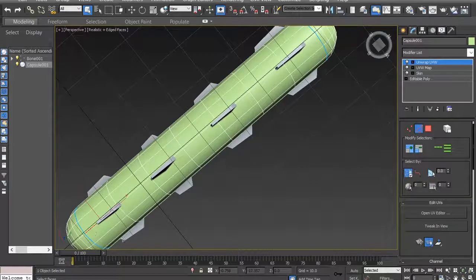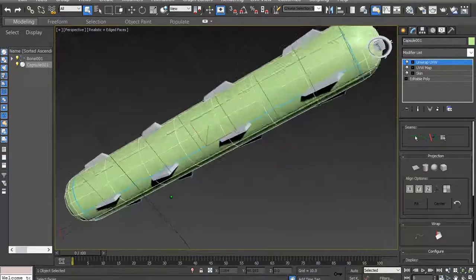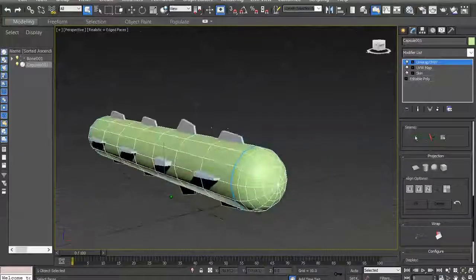And I just click this once. And down here, what I'm going to do is hold down the control button. And then as I add all of these edges, it's going to add them all to the selection. Okay, all of those are ready. Now scroll back down and turn that edge into a seam. So now I've got all three of the seams that I need, and we're ready to go for the next step.